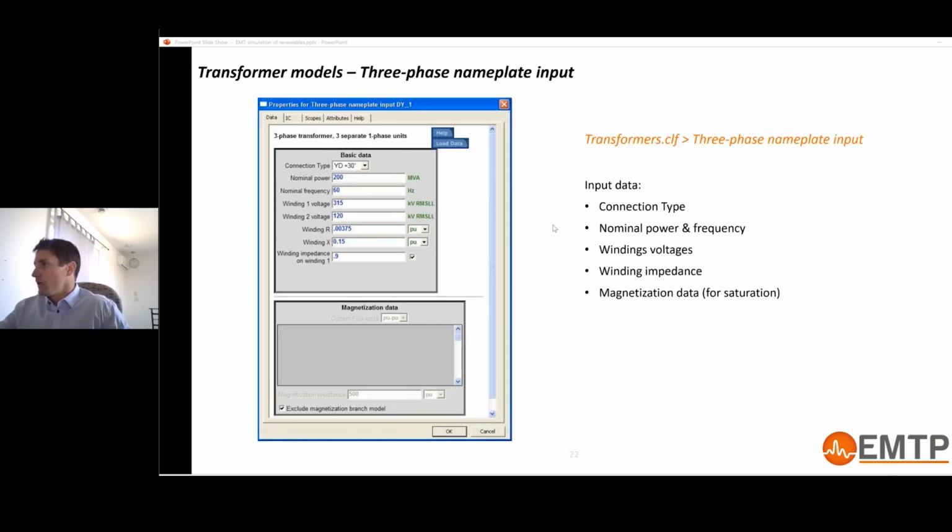Okay, one question here. So the values of impedance are not important for the switching studies. Yes, they are very important, of course, for several things. When you do a switching study, the overall voltages you get depend on inductances and capacitances. So you have to evaluate all inductances close by to your switch and capacitances very precisely. So those are very important.